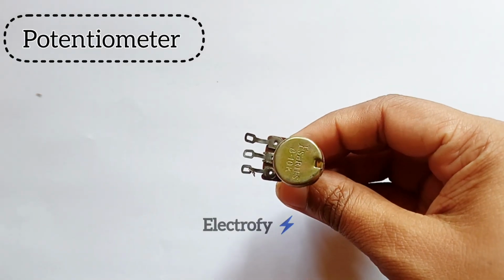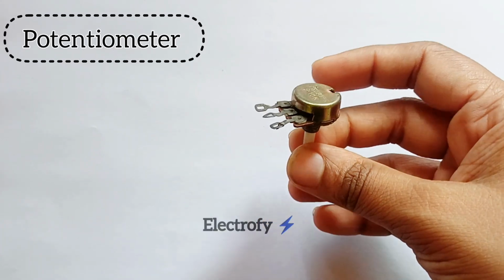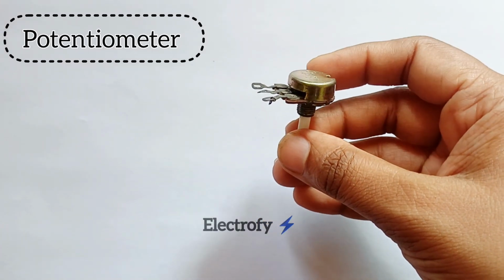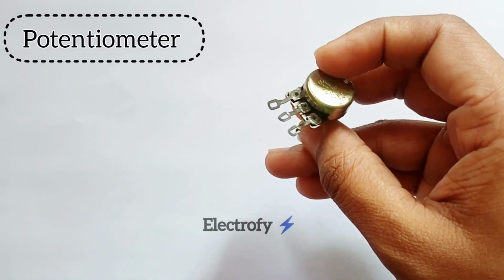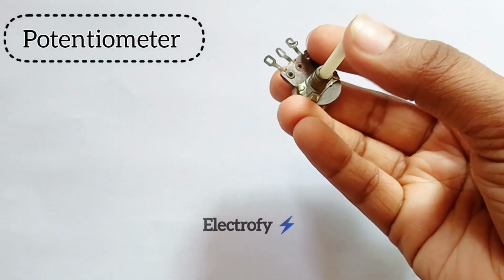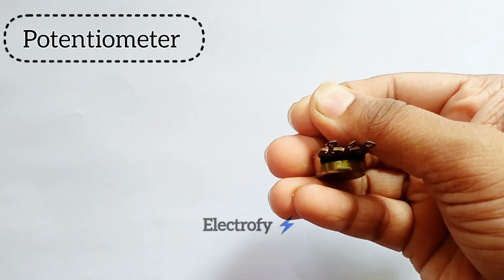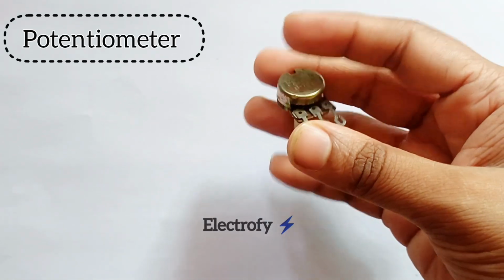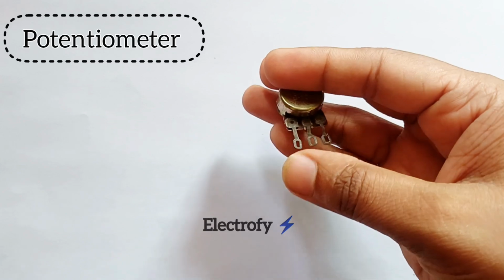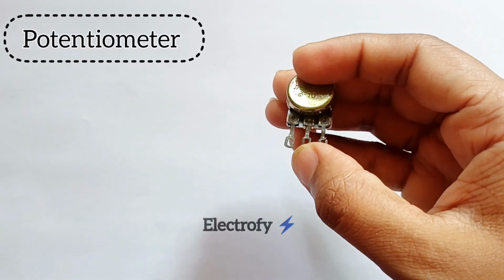So this is the second component we have here, which is a potentiometer. It is also called a pot in electronic technology. This is a 3-terminal resistor which has a sliding contact that forms the adjustable voltage over here. This is the adjustable knob. Now these 3 pins we have here commonly control the resistance. One is VCC, one is ground and the middle one is the variable.